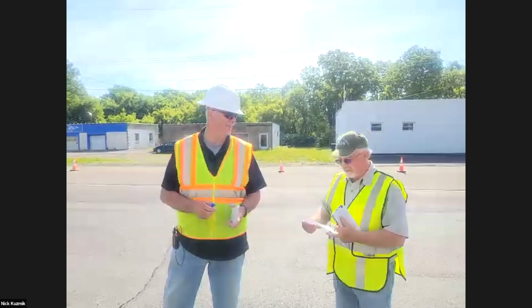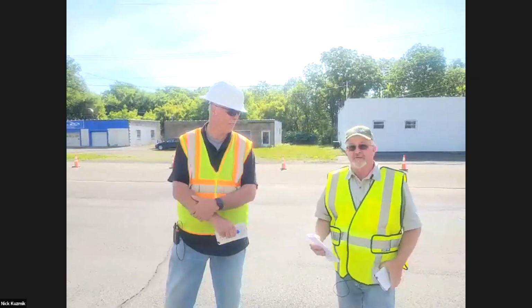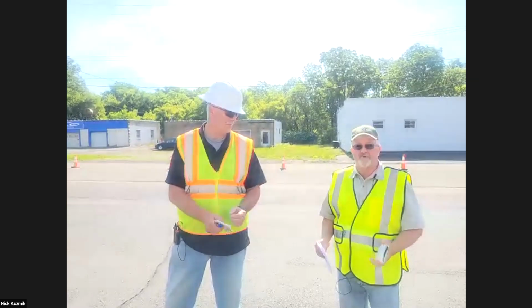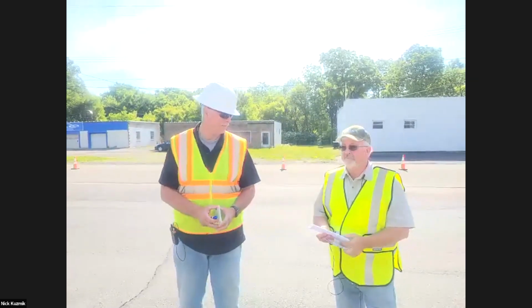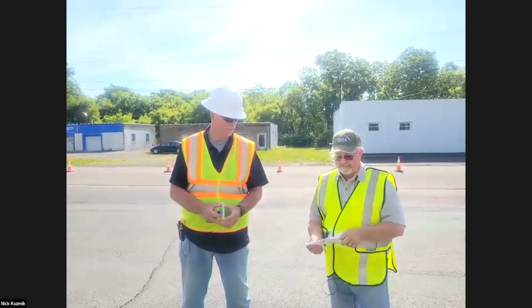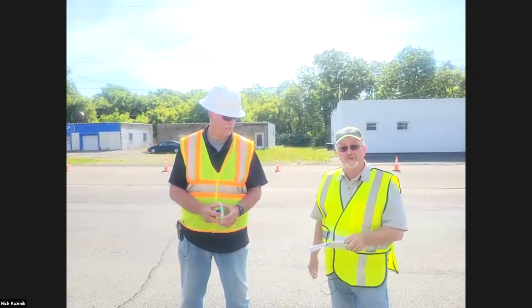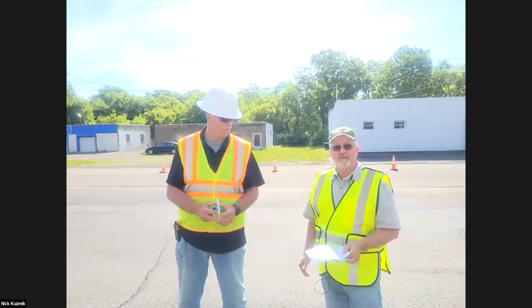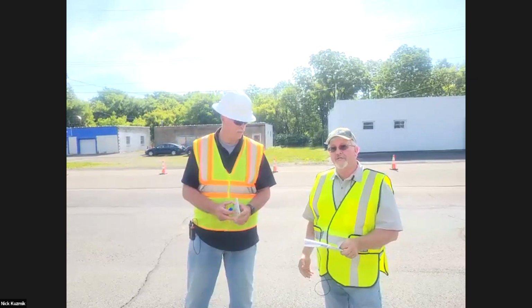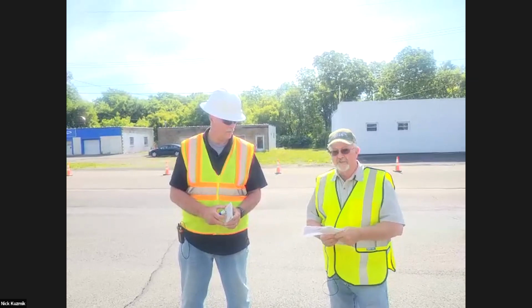So there are some things too. You don't want to, on our list here, you don't want to wait till the trucks show up to set up your work zone. You want to be prepared, have that ready to go before you start working. Everybody informed on what's going on, what's happening. You want to have a plan, decide ahead of time how and where you're going to want to put those displaced traffic. Know how many pieces of equipment you're going to need, how many cones, how many flags, how many signs. And you want those things to be visible too.